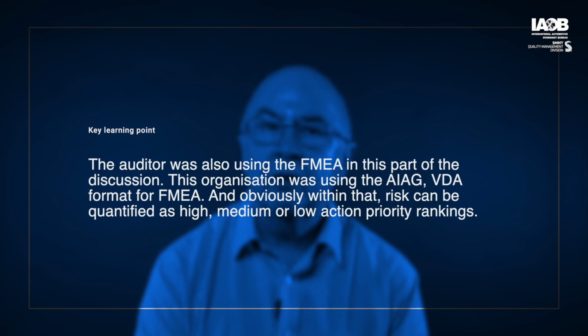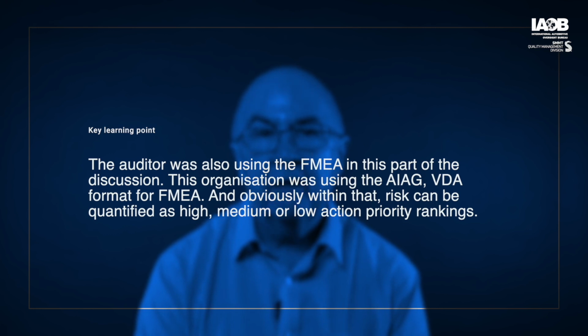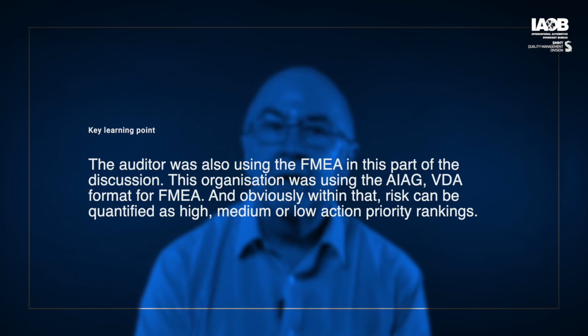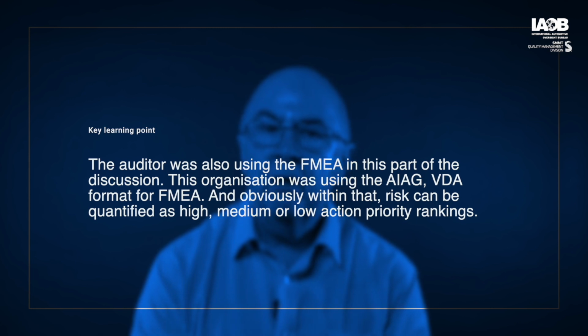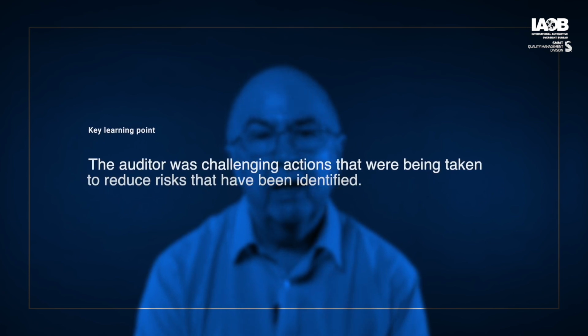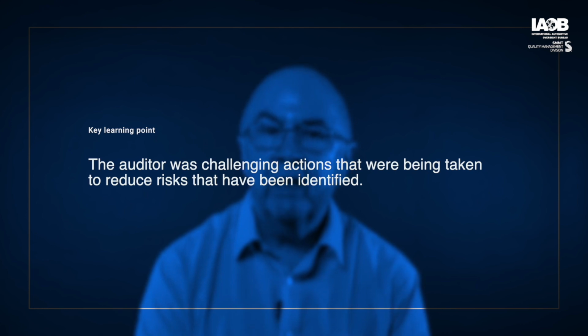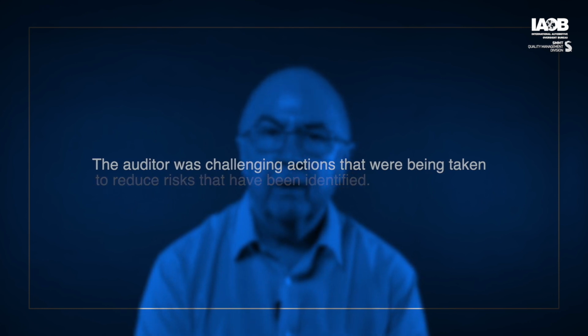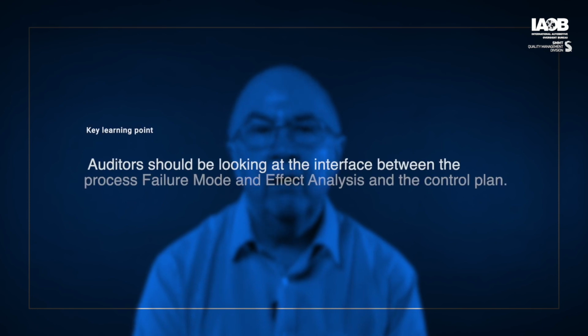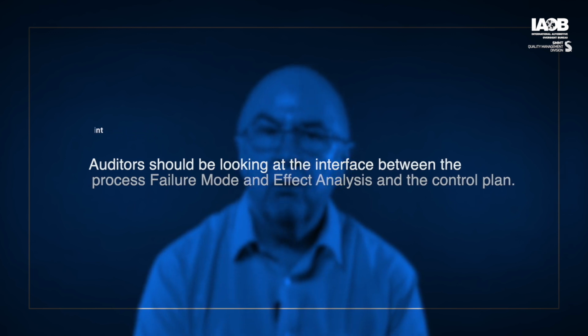This organization was using the AIAG VDA format for PFMEA, and obviously within that, risk can be quantified as high, medium, or low action priority rankings. The auditor was challenging actions that were being taken to reduce risks that have been identified. Also, auditors should be looking at the interface between the process failure mode and effect analysis and the control plan.